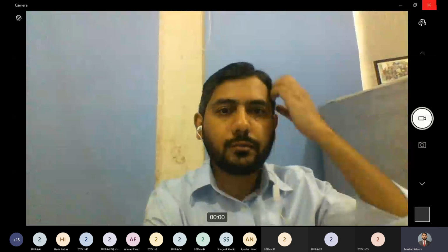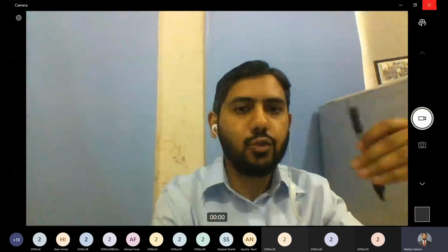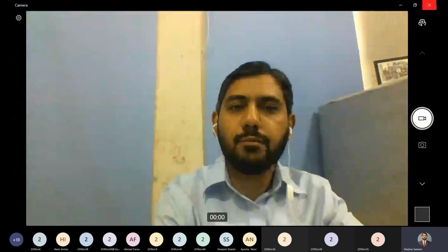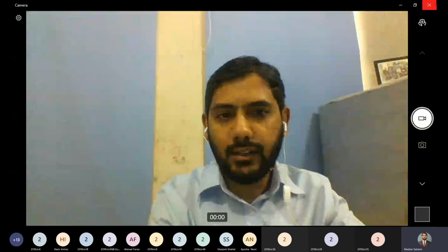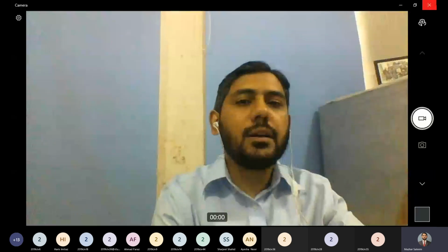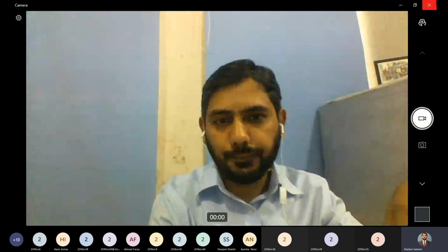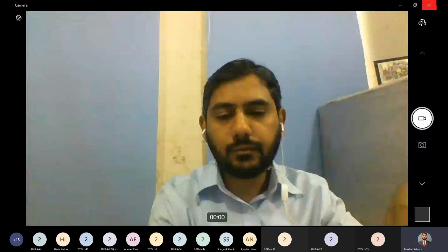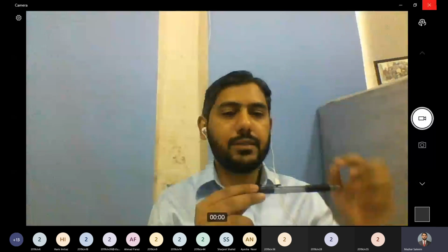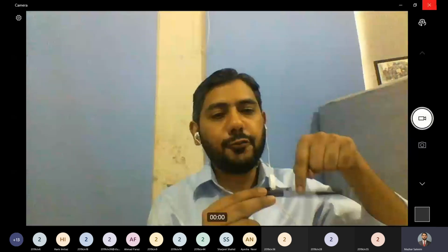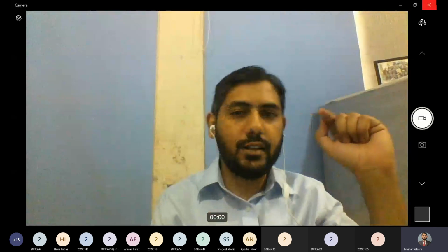In a short while, we will discuss what we mean by shear force and bending. And next thing comes about the orientation of beam. In most of the cases, beams are horizontal. That is why sometimes students assume that beams are always horizontal, but that is not the case. As a structural engineer, the behavior of member is more important for us. We say that beam is a structural member that is subjected to transverse loading, and the internal forces developed are shear force and bending moment.